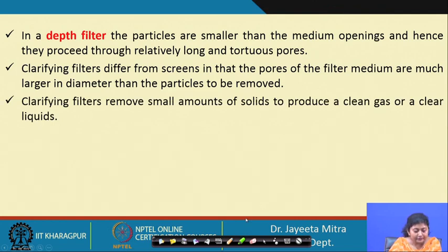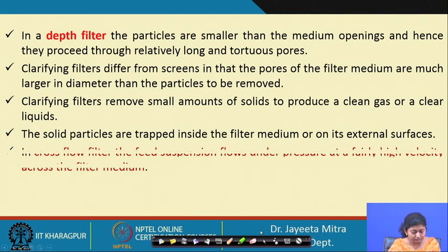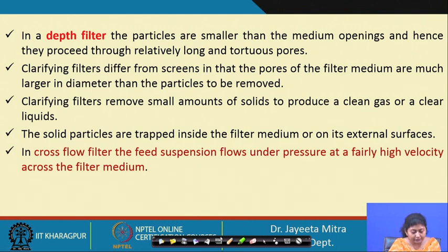And clarifying filters remove a small amount of solid to produce clean gas or clear liquid. The solid particles are trapped inside the filter medium or on its external surfaces. In cross flow filter, the feed suspension flows under pressure at a fairly high velocity across the filter medium.